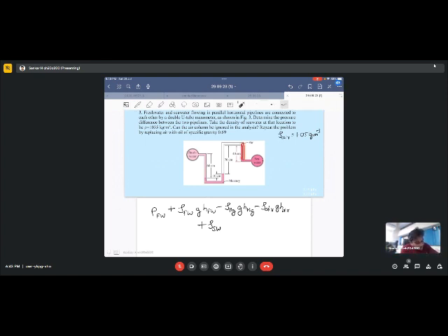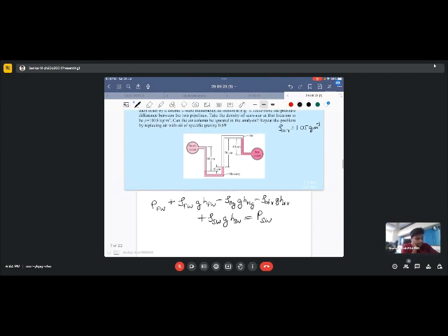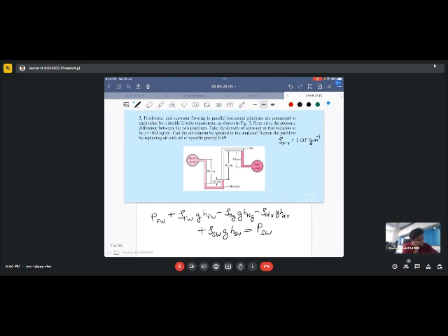seawater's pressure in this limb over here. That's given by the density of seawater times g times the height of the seawater, and we can equate that to the pressure at the right side. If this is kept open to the atmosphere, we just take it as equal to atmospheric pressure. Since it is connected to a pipeline, we have to consider the pressure at that point as the pressure of the seawater in the pipeline. I hope this convention makes sense, and if there are any questions, please let me know.